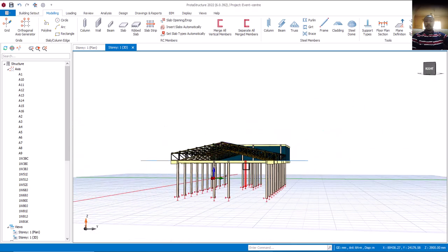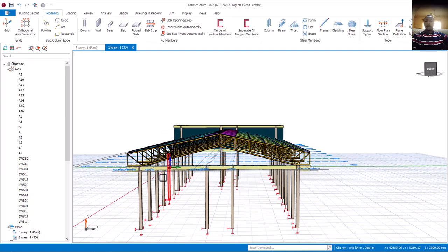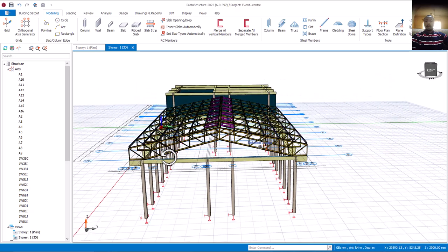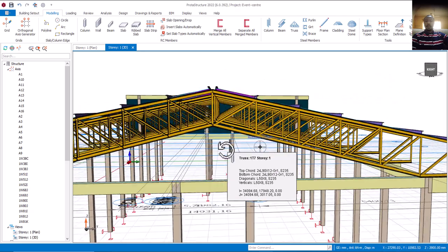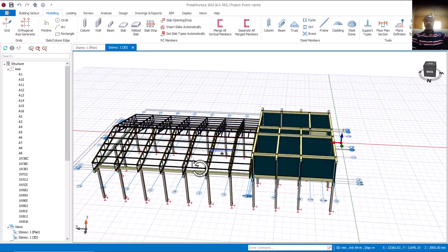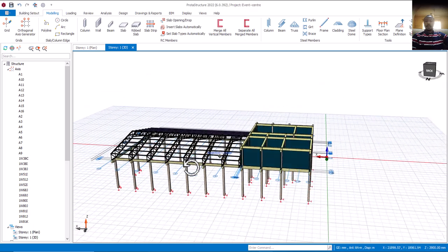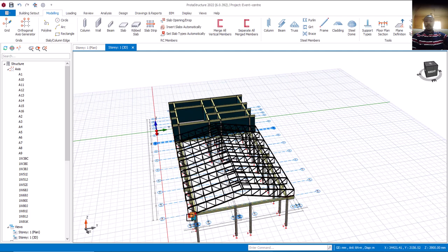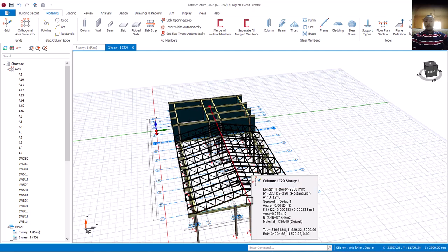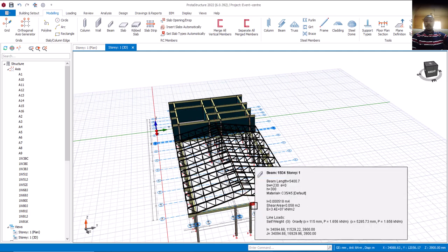So you can now see what we have achieved so far. So can you see it now? Perfectly done. Yes, I was trying to explain something to you that time, the height of your roof. Now if you look, the width of your roof goes a long way in determining the height of your roof. So if from this point to this point is about 30 meters or 50 meters, automatically the half of it will be 25. If from here to here is 50 meters, at the center here will be 25.